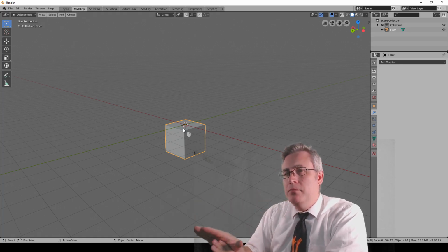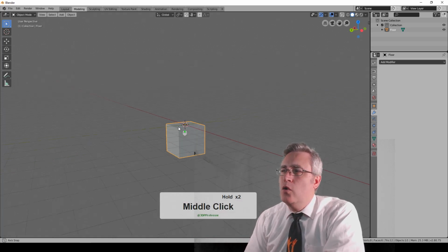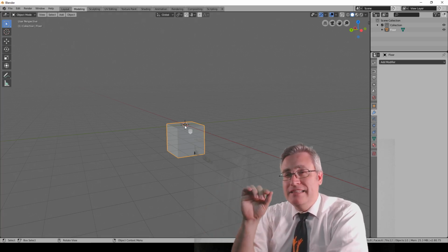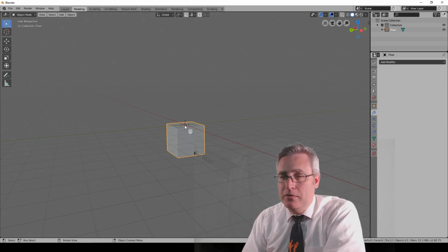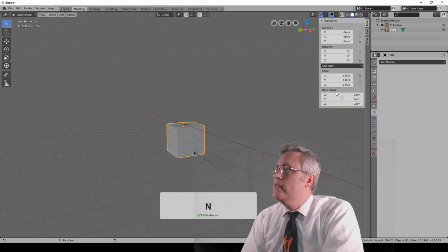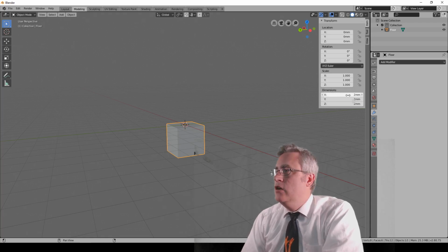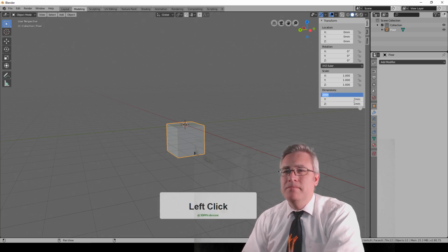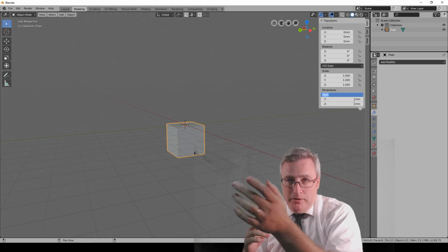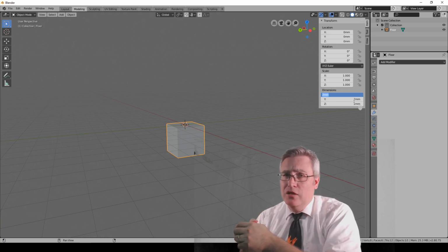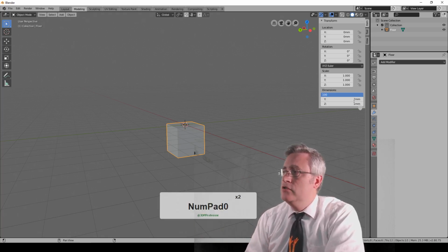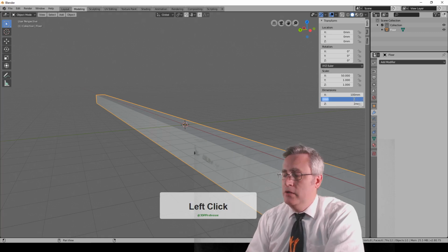It's below the XY plane, but what's more important is that its origin, that point that defines where everything scales up from, is still at that XY plane. Watch this. Let's open up that sidebar again, and let's edit the dimensions in here. We want the X of this to be, well, you want its X and Y to be the dimensions of your build plate, but I designed for a lot of 3D printers, so I like to make this floor 100 millimeters by 100 millimeters.